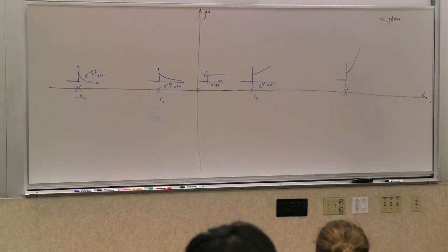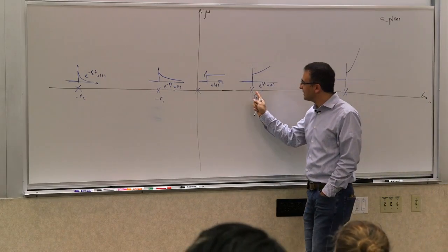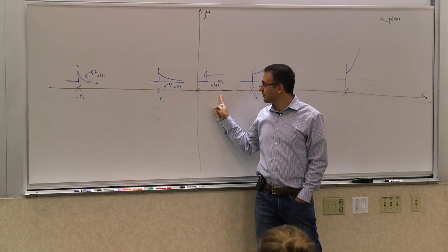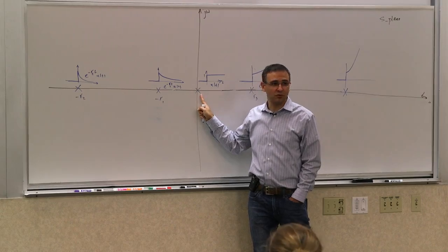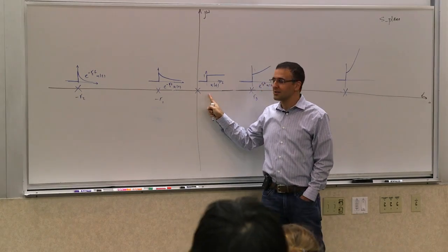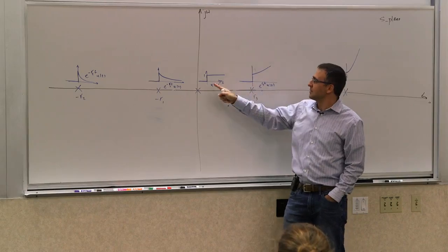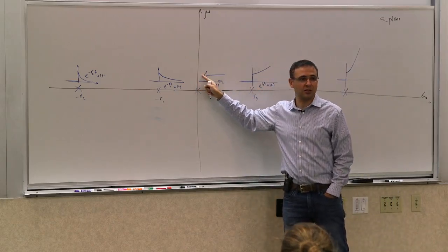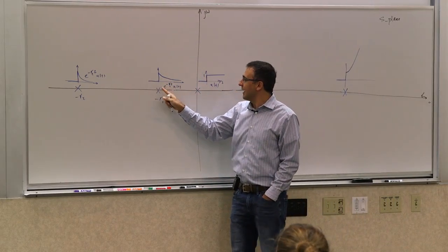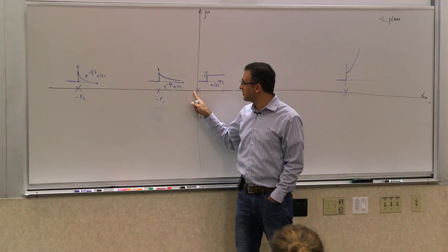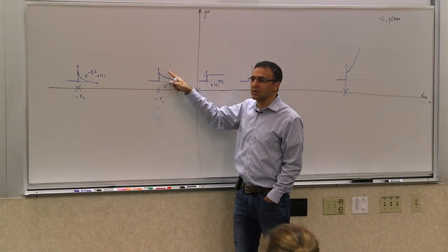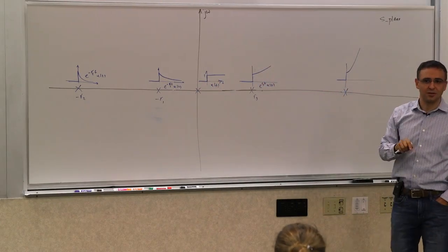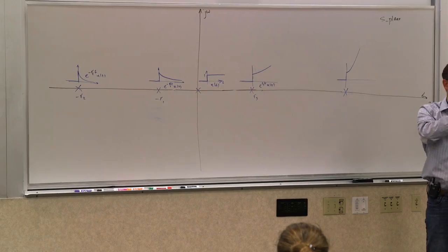So you see the transition. And this should make sense because this should be continuous. As you bring this closer and closer, when you get very close to this point, it should almost look like that. Why? Because it's so slowly growing at that point that essentially it would be very slowly going. So when you get it to 0, essentially it becomes flat. And when you go past, if you have a pole very close to here, this is decaying so slowly that essentially it's just converging to the step. So that's for real poles, single real poles.